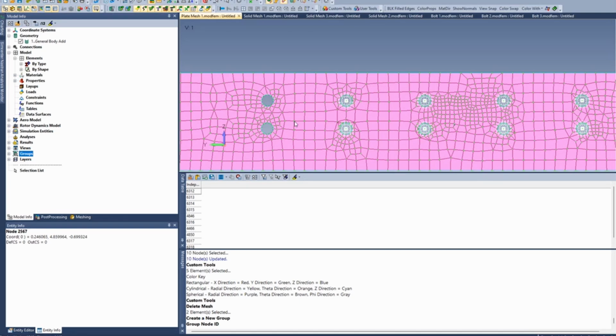Okay, the next question is, I use 0 DOF spring damper for bolt forces instead of modeling bolts. What advantage or disadvantage would it make in your experience? Using the CBUSH rather than modeling the bolts. Well, if you use the beam, you could do it either way.